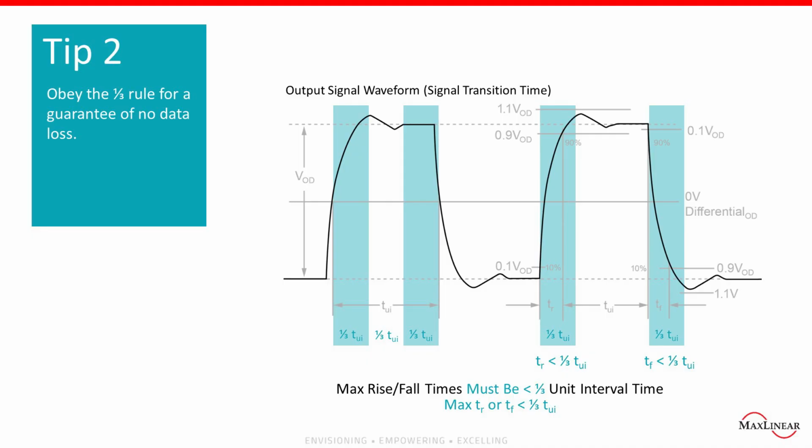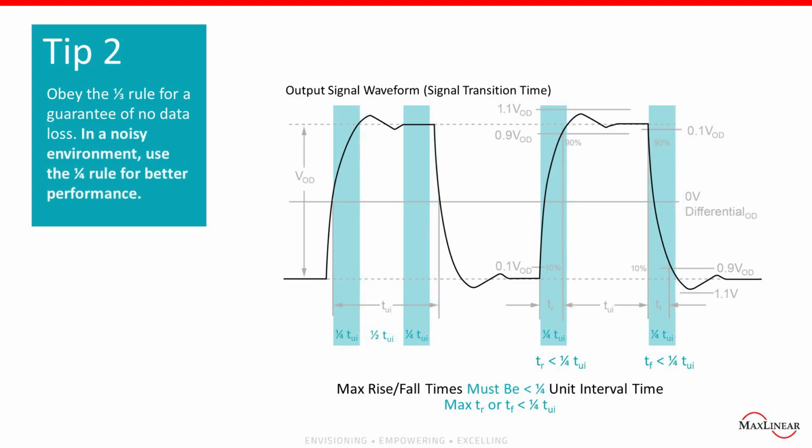Tip 2. Obey the 1/3 rule. 1/3 rise time, 1/3 fall time, and 1/3 bit time to guarantee no data loss. In a noisy environment, use the 1/4 rule. 1/4 rise time, 1/4 fall time, and 1/2 bit time for better performance.